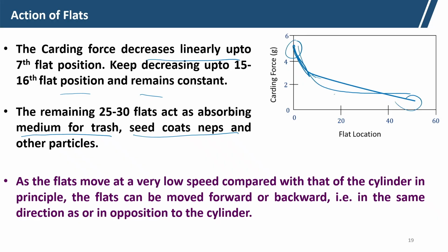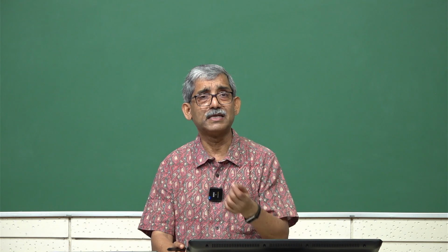The flats move at a very slow speed compared to the cylinder, so we cannot move the flat at high speed. The flat can be moved either in the same direction as the cylinder or in the opposite direction, because compared to the cylinder surface speed, the flat surface speed is negligible.